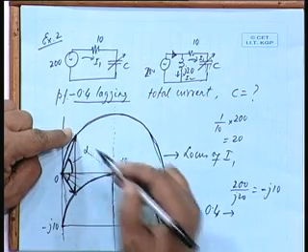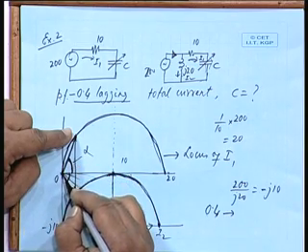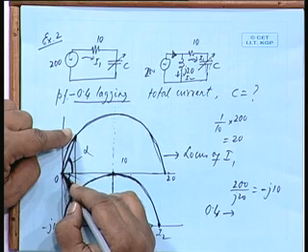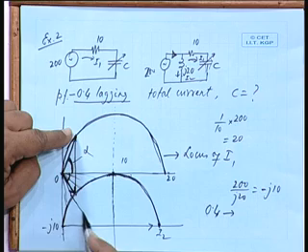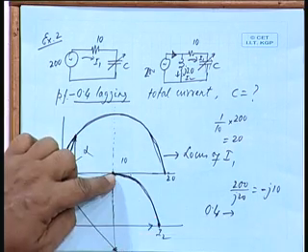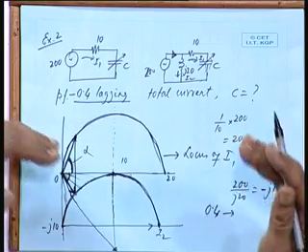Then how do I get the corresponding impedance? So, draw an angle alpha here, whatever it be, all right, and then stretch it. This is the point x, is it not? If you remember, going from admittance back to impedance, a first quadrant angle becomes a fourth quadrant angle and a fourth quadrant angle comes to the first quadrant, as you keep interchanging z to y or y to z.